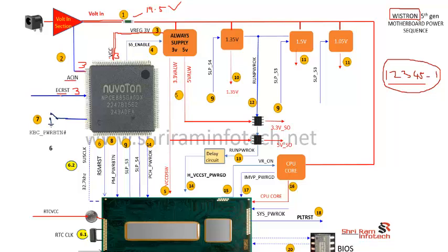In electronics, every chip requires a reset signal to clear all the junk information within the chip. Reset signal is normally 0 volt. If we give 0 volt to any embedded controller, the PCH or the CPU, it gets reset, and then to come out of the reset state we have to increase that voltage.